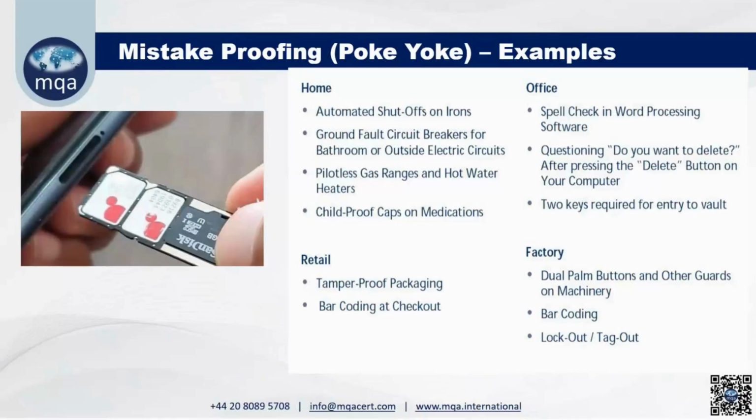Now one more poka-yoke used in safety is the lockout tagout system. You know lockout tagout? It is one of the important safety kaizens. So what is there in tagout? Whenever an electrician wants to do work in the panel, he will switch off the machine, switch off the panel section, and lock the switch with a lock and key, and he will keep the key with him.